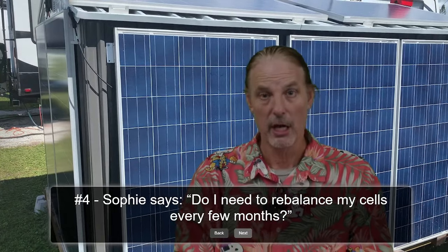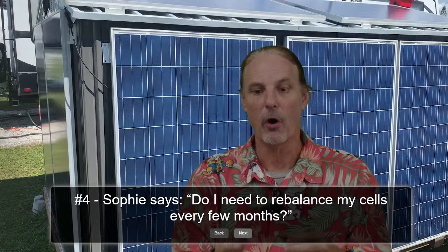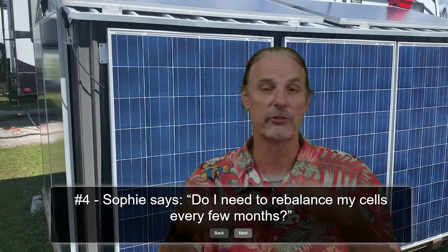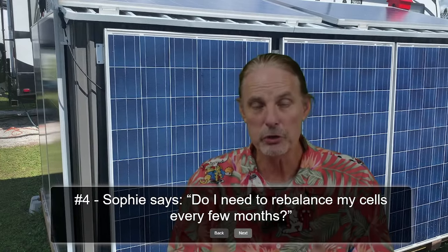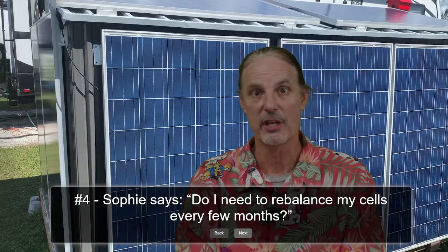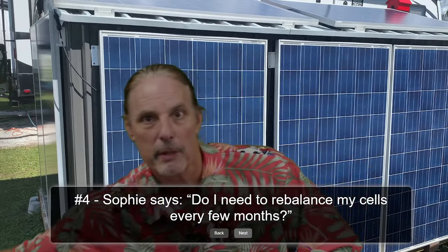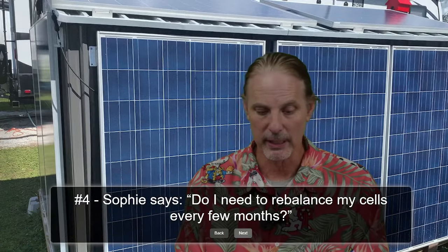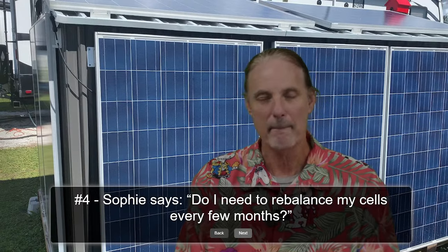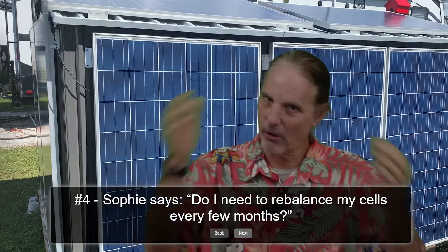This is a good thing, but you still have to deal with the fact that there are going to be variations within each of those cells, and you're going to need to do a balancing. Most BMSs will start balancing when the first cell hits 3.4 volts. So if you're talking about 3.4 volts in a 48 volt battery, in generic terms, you're looking at 3.4 times 16, about 54.4 volts, give or take. And that means that all of the cells are there.